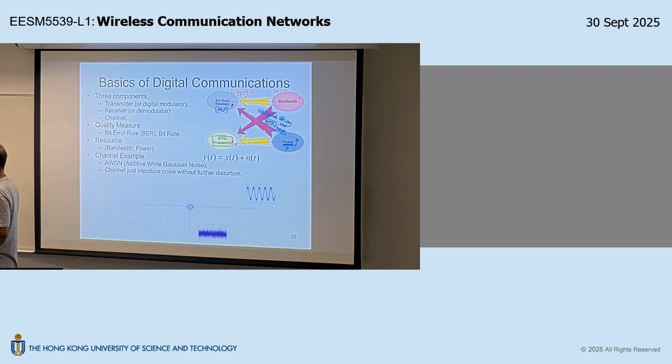Of course, in this case, you will pick this one, right? Because this one will give you extra bit rate at the expense of extra power. Now, in this terrestrial setup, power is not that expensive, right? Because you're using utility power. But on the other hand, the bandwidth is more expensive in this case, because, for example, the carrier frequency is much lower, because you want a more favorable propagation physics. So in this case, the frequency may be only 2 gigahertz carrier frequency.